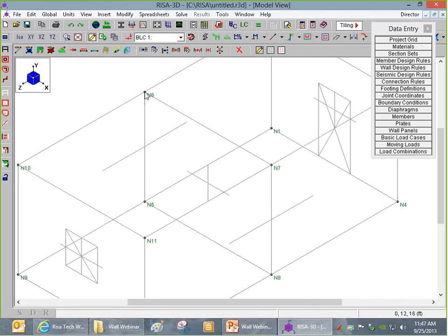And if I didn't want this wall to mesh and merge in with the wall running in the other direction, I'd want to make sure to leave a small gap between the 2 walls so that they didn't actually touch each other. Because if they don't actually touch each other, then they're not going to mesh with each other.